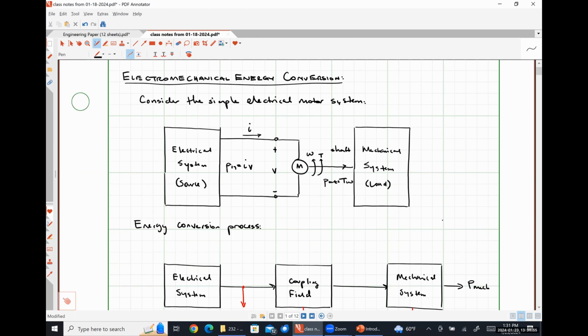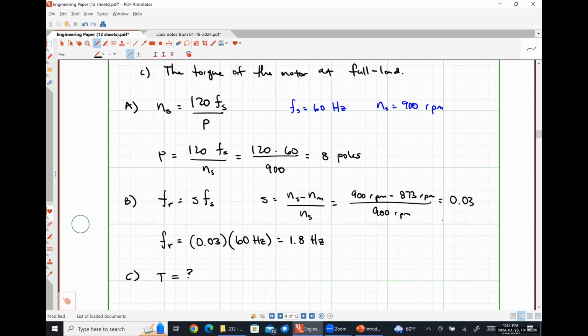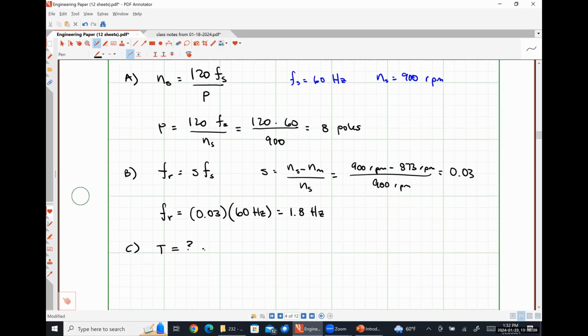to the front page of this thing, first thing that I talked about was that our output power, P_out, was equal to torque times angular frequency. We have an output power, 50 horsepower. We have an angular frequency. So it seems to me like we should be able to figure out torque from those two numbers without going through a whole bunch of weird conversion things. Right? And by the way, the whole bunch of weird conversion things wind up giving us that exact relationship. So we can say that our developed torque is our output power divided by our mechanical rotation speed, omega_m.